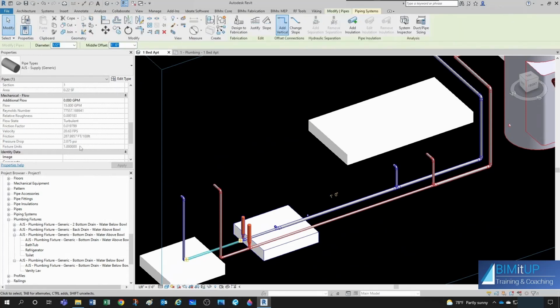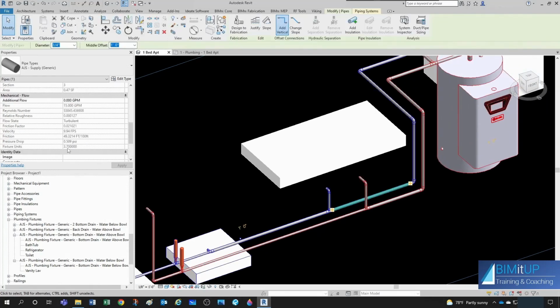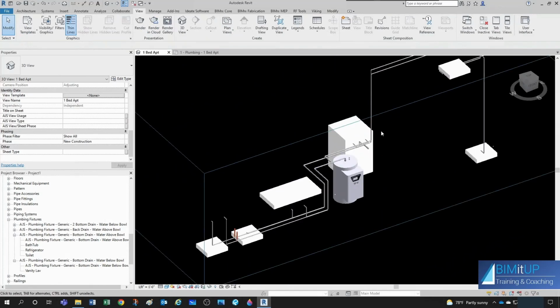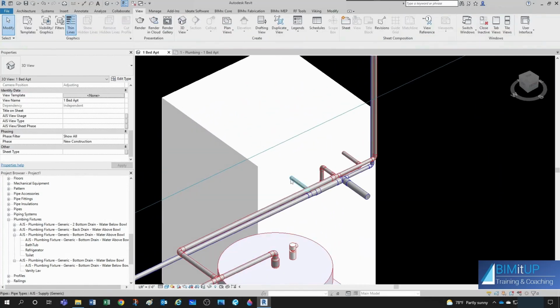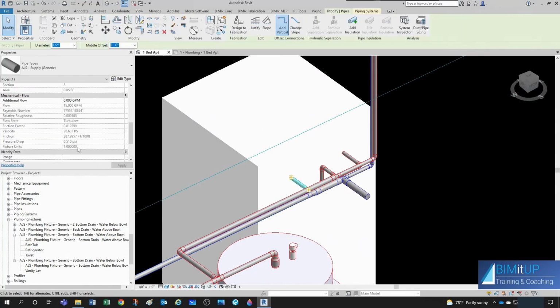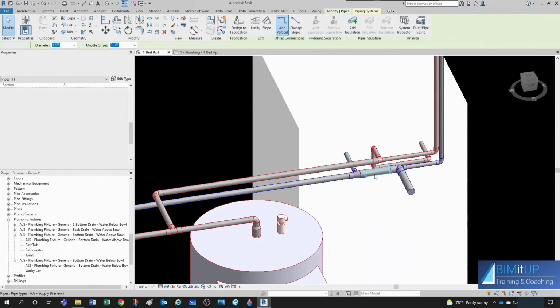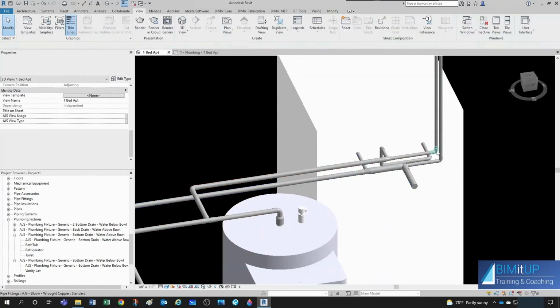And then on my cold water, I have something similar. So here I have one fixture unit. I encounter my toilet, and that brings it up to 3.2 because the toilet's 2.2. Then this one here is 3.7 because I added 0.5 from the lavatory. And then the sink over there is bringing in also one fixture unit. And then the washer is introducing one more. And then if I add one more from the washing machine, I have then 4.7. And then if I join it together with the one that I had here, I have 5.7. So we're good to go.